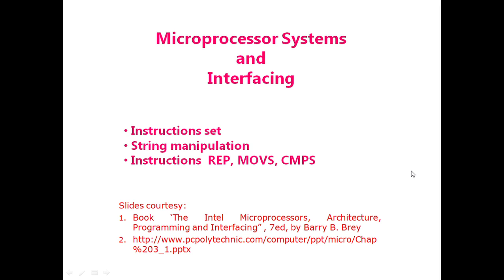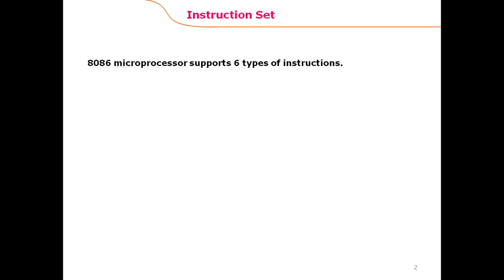The topics of this lecture are the instruction set of the Intel family of microprocessors. In particular, the focus is on the instruction set of the 8086 microprocessor. Also, string manipulation instructions, including the repeat prefix, MOVS, and compare string instructions, are discussed in this lecture.